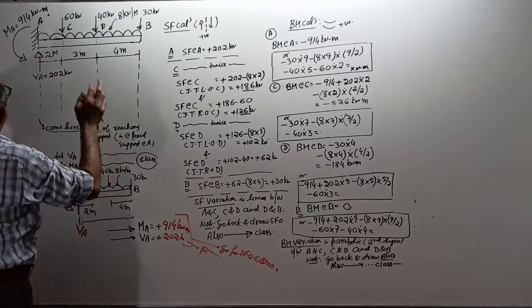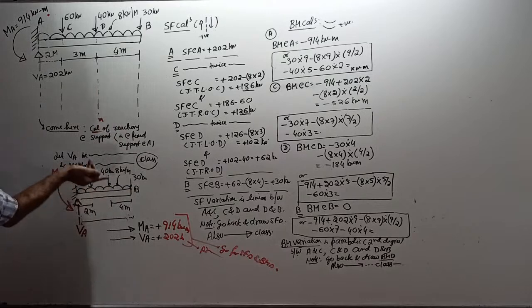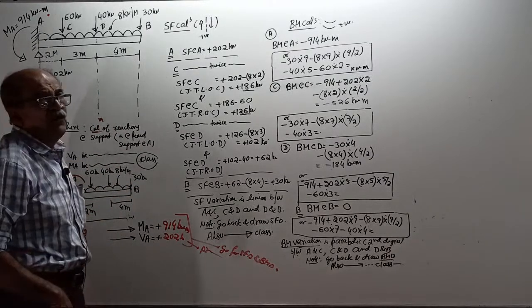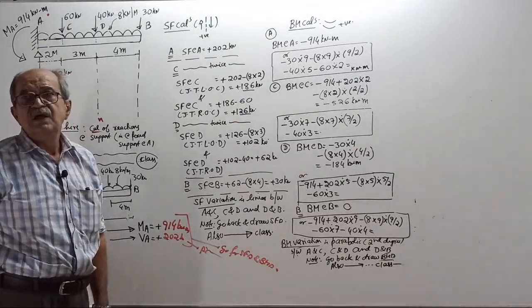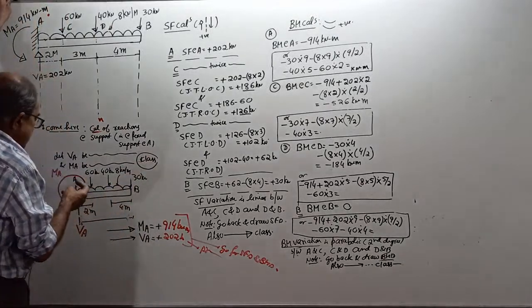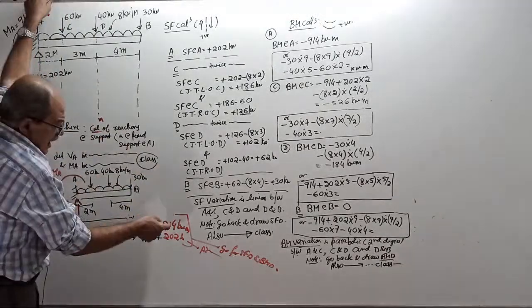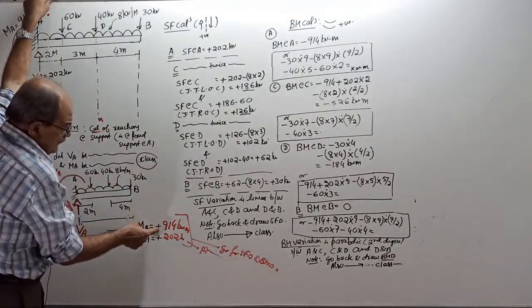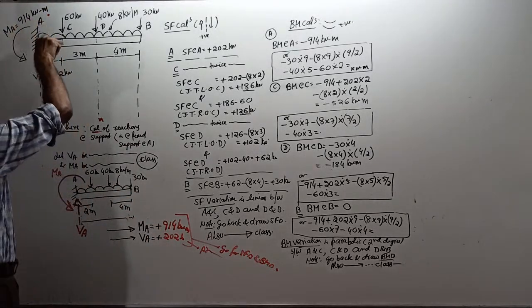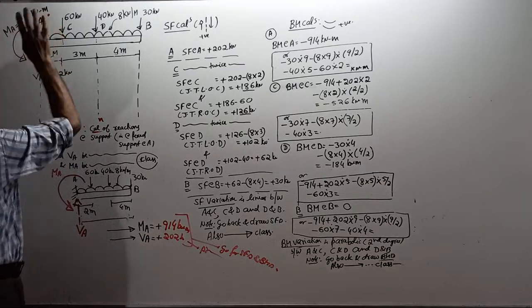No plus now. We considered MA in anti-clockwise direction. Sometimes people will tell, sir, you take clockwise positive. Keep quiet. Do not tell sign convention. It has no effect. I considered anti-clockwise. I got positive. This positive means what you assumed is correct. Enter anti-clockwise of 914 kilonewton meter.